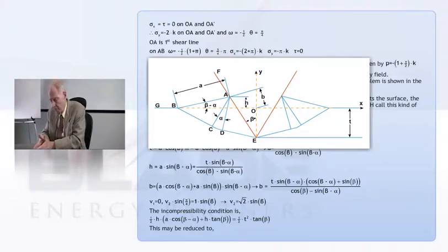Anyway, as it goes down, once more, the material's got to get out of the way because the material's incompressible. So a little ledge rises on each side of the punch as it goes straight down. And you can see it's the same old thing. On each side, there's two constant state regions, and in between, there's a centered fan.